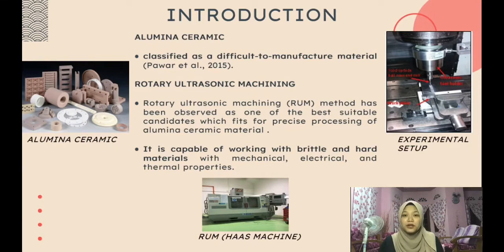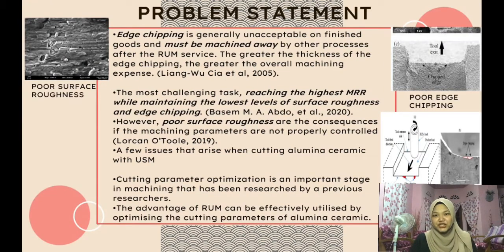It is suitable for micro or macro machining of both brittle and non-brittle materials. By first incorporating the ultrasonic frequency to the rotating cutting tool, the vibration oscillation amplitude of the tool is altered, which imposes a static pressure on the workpiece surface grains, where the workpiece surface is then hammered into. Done with introduction, now I will move to problem statement.